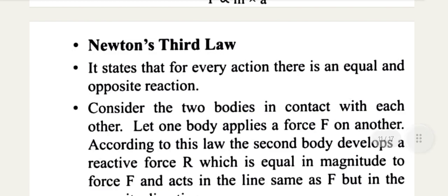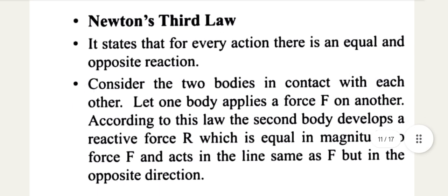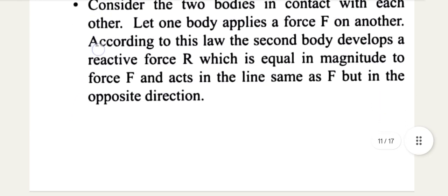And Newton's third law. It states that to every action there is an equal and opposite reaction. Consider two bodies in contact with each other. Let one body apply a force F on another. According to this law, the second body develops a reactive force R which is equal in magnitude to force F and acts along the same line as F but in the opposite direction.